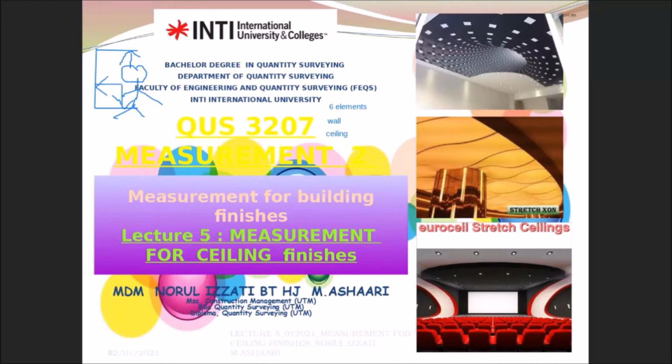So when I say 6 elements, that means each of the element will have sub-element. Okay, this is the first overview. So each of these we have internal and external. Okay, sorry, I and E. So that means for internal, you have internal wall and you have external wall. Ceiling also you have internal ceiling and external ceiling. Floor also internal and external. Okay, so for today, we are going to measure for the ceiling finishes. You can see the overview here on the right hand side.